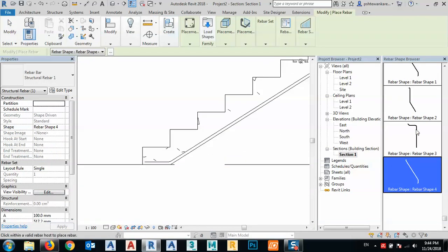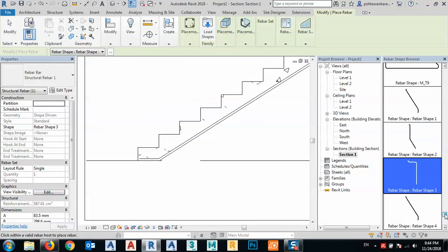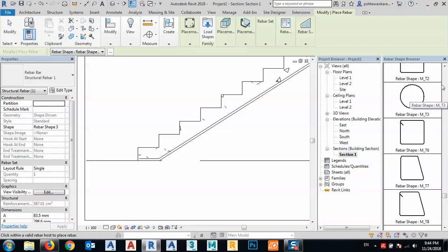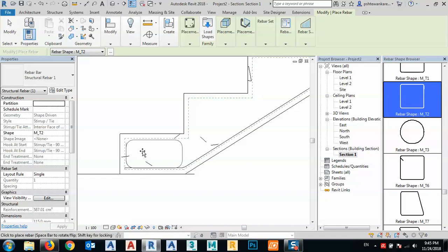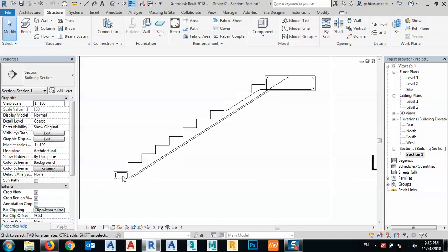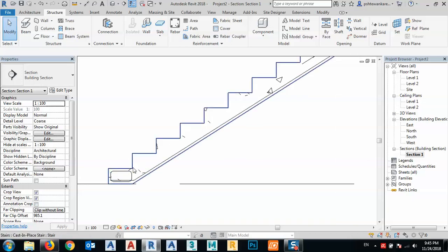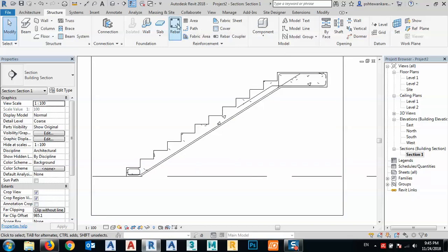Yeah, from rebar, let me just, sorry, here I want to select rebar shape. Yes, you see, just put it like this and it selects everything, and it's okay. Now again, maximum spacing, maybe this, because it's a beam, maybe I can use 150. I think it's okay. I can put another steel like here. No problem, you can put it.